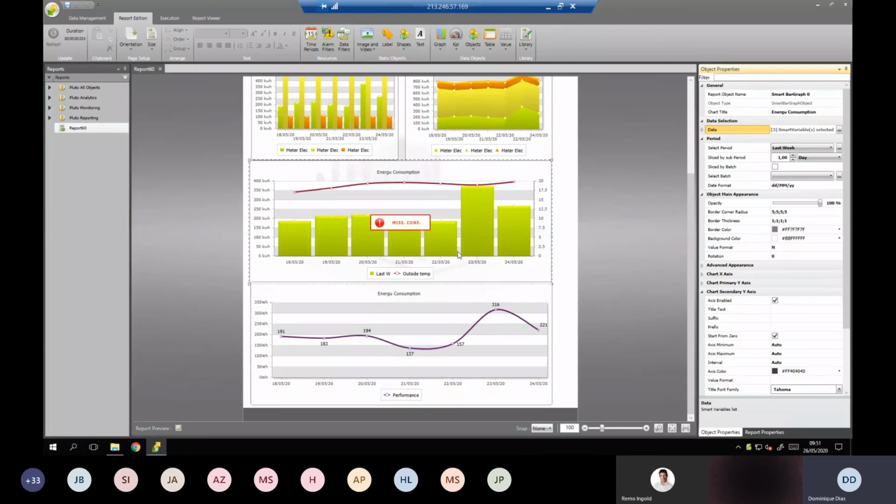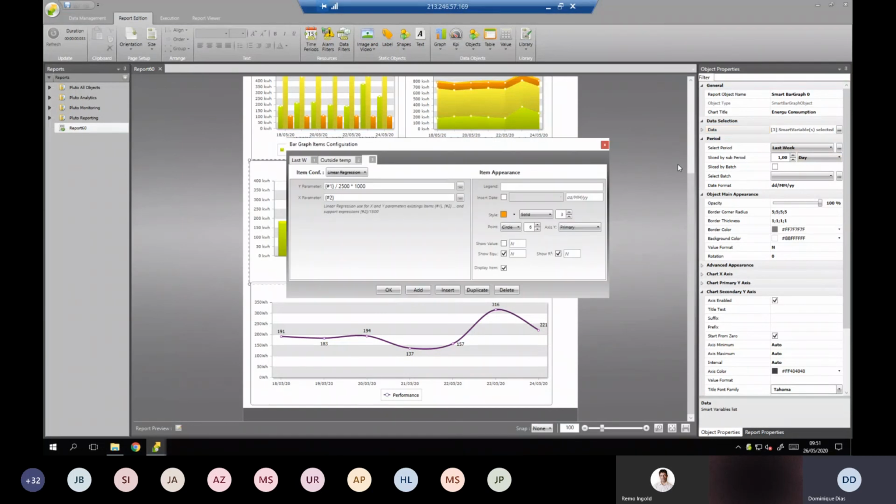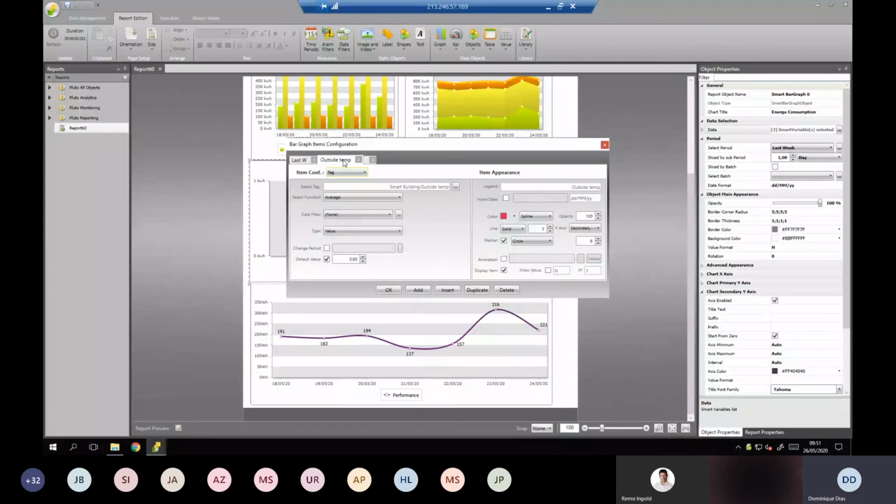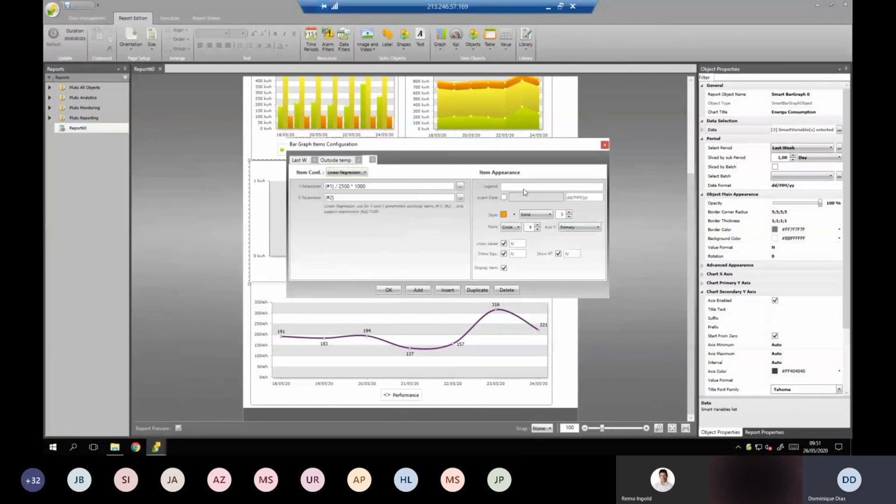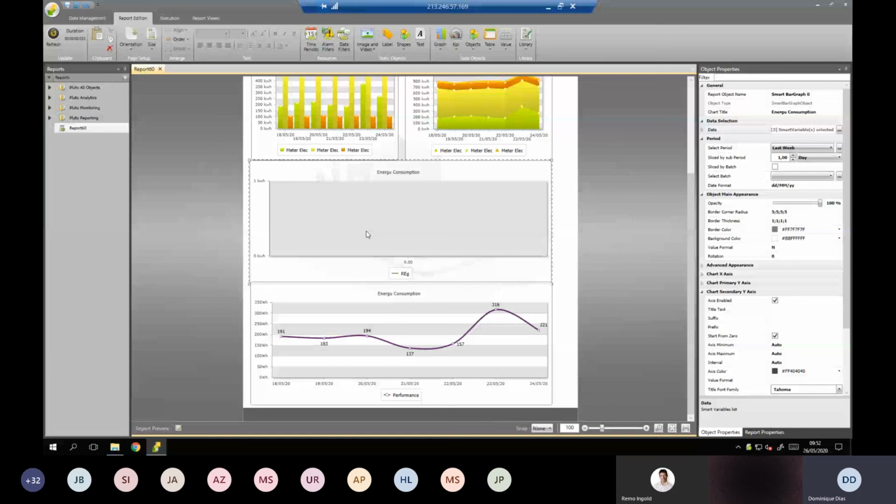What you have to do next, you have options for those who want to see the value and what we call the equation with the R2. This is something really related to linear regressions. You can hide the two first charts and see the linear regression. When you refresh directly, you have your regression done, where you can see how your temperature is impacting your energy consumption.